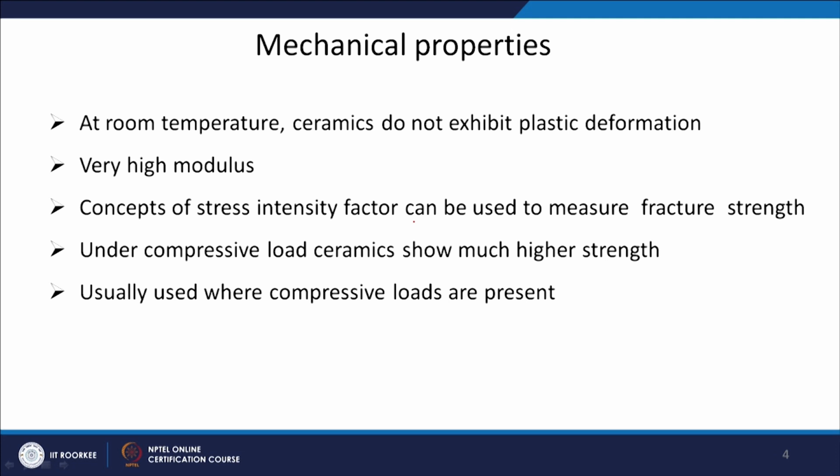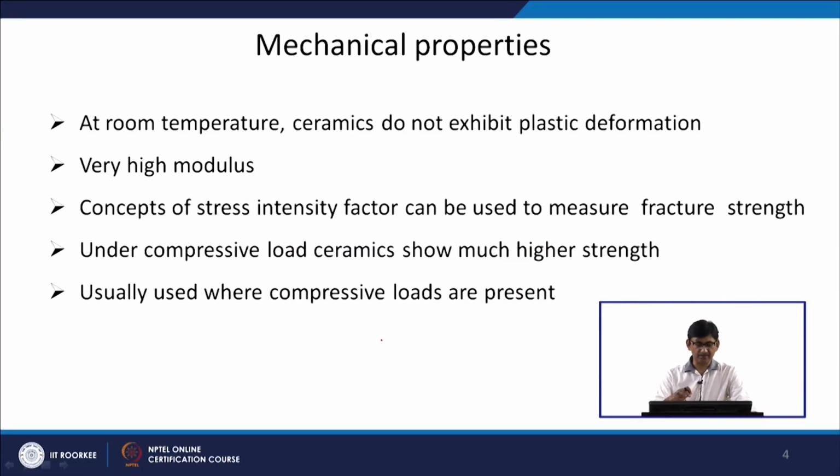Again, the failure is because of the defects present in the ceramic material, in the form of small cracks or flaws, and when you apply stress they propagate and your material fails. Under compressive load, ceramics show much higher strength. They are able to take the compressive load very nicely, because under compressive load your cracks do not open up, in fact you are closing them. So ceramics can be used very nicely under compressive loading conditions, and that is why they are used where compressive loads are present.